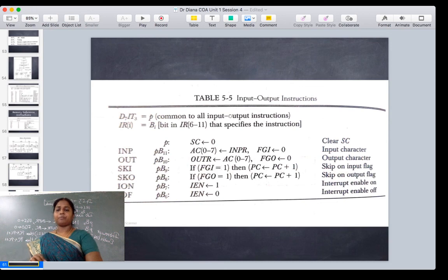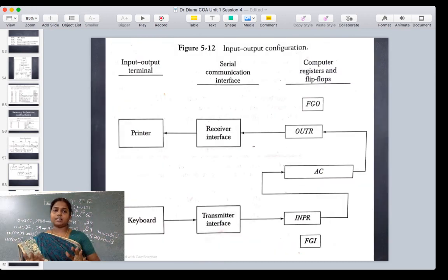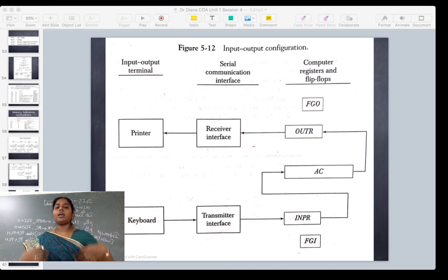next session. For now, you just understand that an interrupt is a signal sent to the CPU so that it can pause whatever it is doing and then attend to it. Every time the CPU receives an interrupt and goes to that particular device for doing what the device is asking, it is called servicing of the interrupt.